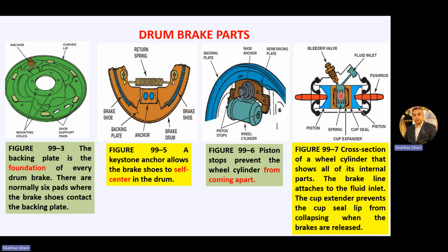Fluid is coming with pressure here, and when we press the pedal, the fluid comes with the pressure and moves the piston outwards. Its push rods energize the primary and the secondary shoes. So this is the portion where you have a fluid.